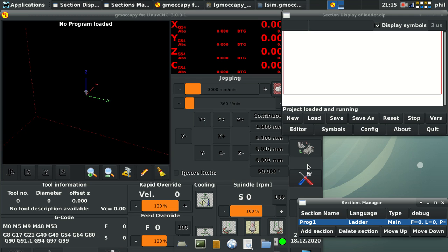to utilize a deadman switch on my PlayStation controller to basically lock out the override increase and override decrease. That way there's a safety factor built into my PlayStation controller, so I don't just hit a button and have the spindle inadvertently increase in speed or decrease in speed. There has to be a physical deadman switch or acknowledgement switch in order to activate those two buttons, and we're going to do that with Classicladder.